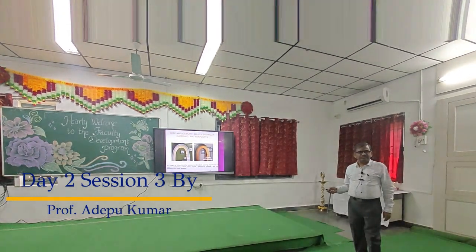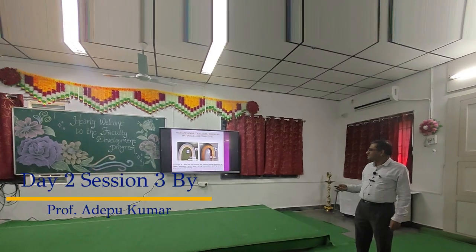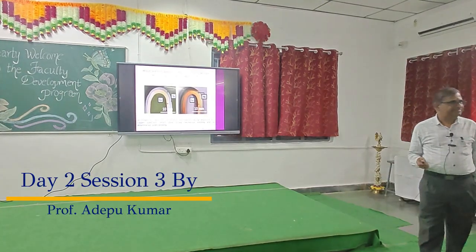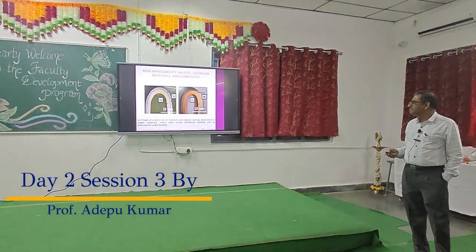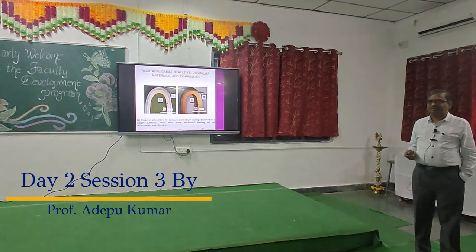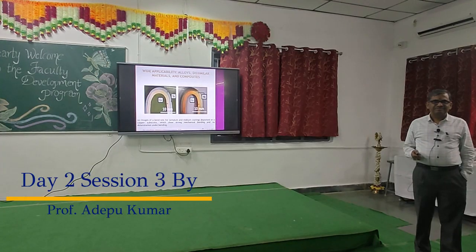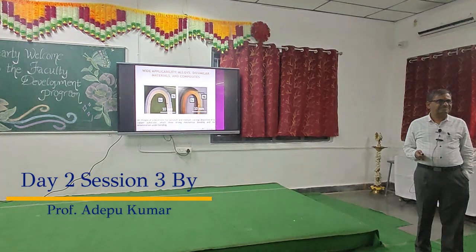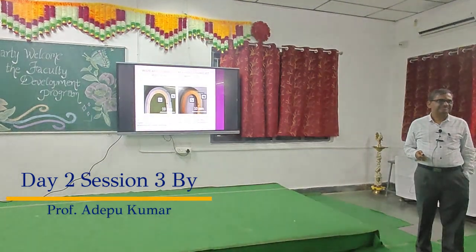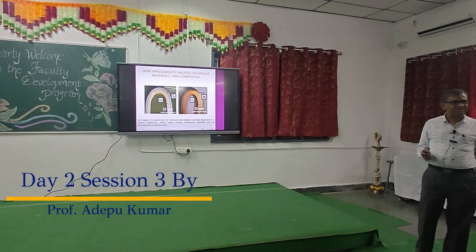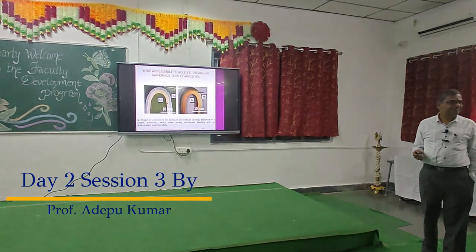If you observe these materials, one is copper and tantalum. This is my application for one of the sectors. I want to deposit copper and tantalum. There is a huge difference in melting point temperatures in both cases. So it is impossible to deposit through direct energy or powder based fusion process.